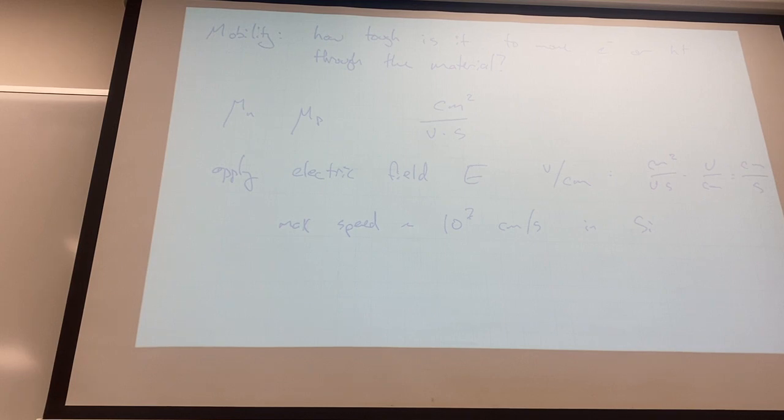So here's a funny thing. When you add dopants, you add more boron or you add more arsenic or phosphorus, the mobility goes down, which maybe kind of makes intuitive sense. There's just more stuff in the silicon lattice, and it's harder to move things in response to an electric field. But you are adding so many extra carriers, so many holes or so many electrons, that the effective current still goes up. You take a small hit in mobility, but a huge boon in just quantity of carriers that are able to flow in response to this electric field. And so you still end up with a material that goes down in resistance. It ends up being able to conduct more stuff. It's moving a little more slowly, but there's just a lot more of it around. It's a weird kind of counterintuitive thing.